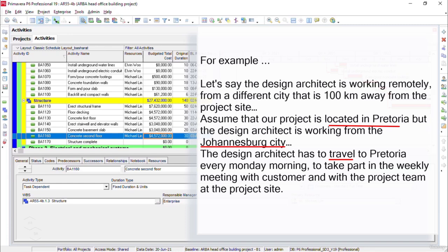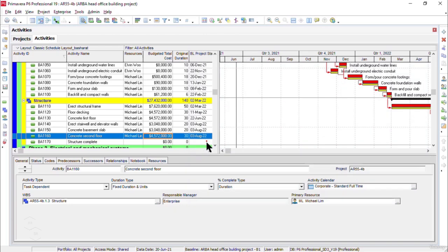I mean, we record this cost in the activity details form in the expenses tab only. So the expenses are costs that are also assigned to the activities, and please don't worry, since it's very simple to assign cost in Primavera P6. What I mean is that we assign cost to the activities exactly the same way we did for our resources in our previous discussion. Okay, so you have the concept now of what the expenses are. Now let's learn the procedure in Primavera P6 where we can actually assign the cost to our activities in the project. Okay, so good.